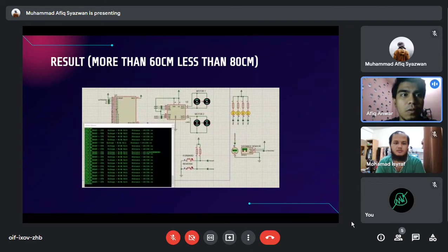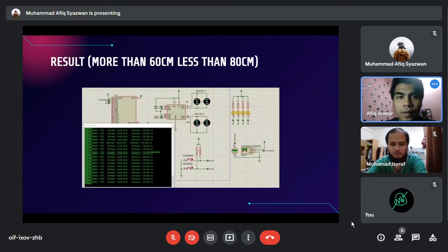The GP2D12 will function to determine the distance between the car and the object. Based on research on the internet, a formula that converts the analog value of GP2D12 to voltage value and the distance in cm is found. The voltage for distance measured is given with the reference voltage VR of 5 volt.